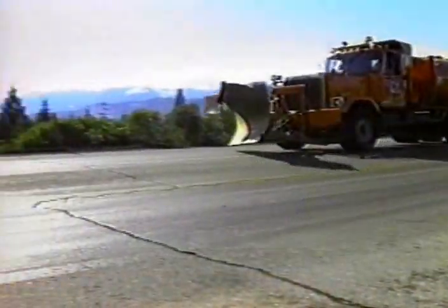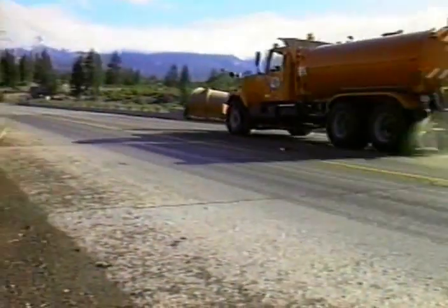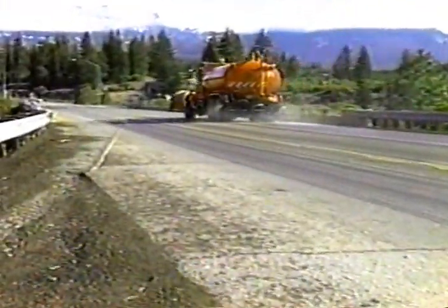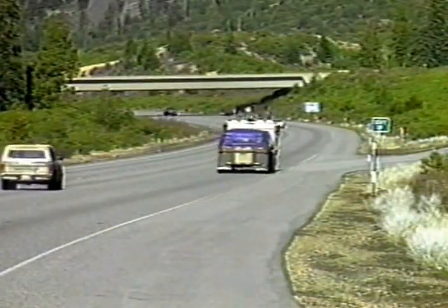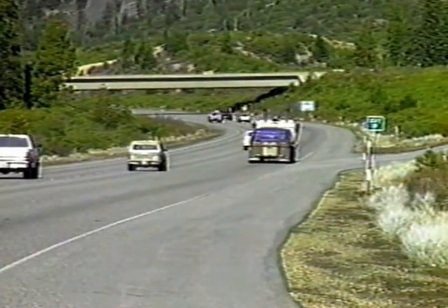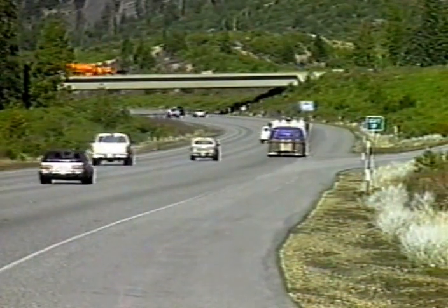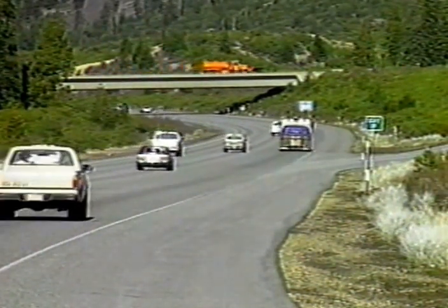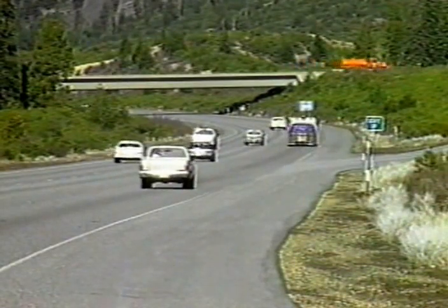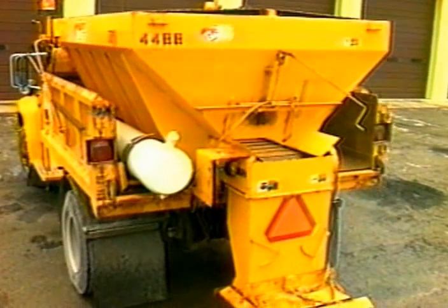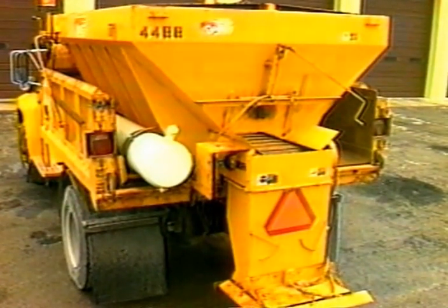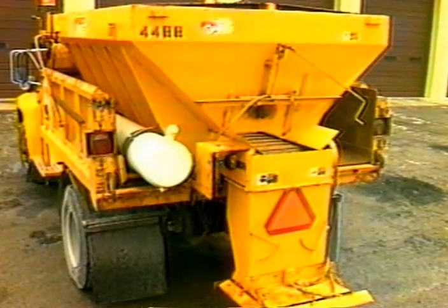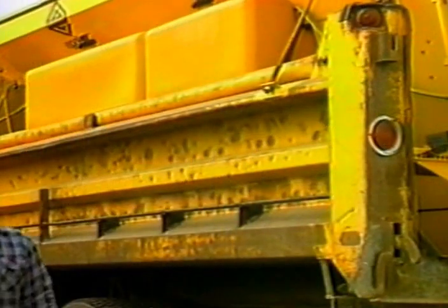There are circumstances when it is appropriate to apply a chemical on dry pavement. These include pre-treating as part of a pre-season preventive operation, beating rush hour traffic, and pre-treating for bridge deck or cold spot icing. In these circumstances, applying a pre-wetted salt or a liquid chemical will substantially reduce material loss, resulting in greater effectiveness. Tailgate spreaders and hopper spreaders can apply free-flowing granular materials in paths from 4 to 40 feet wide. Both types have been used successfully in anti-icing programs.